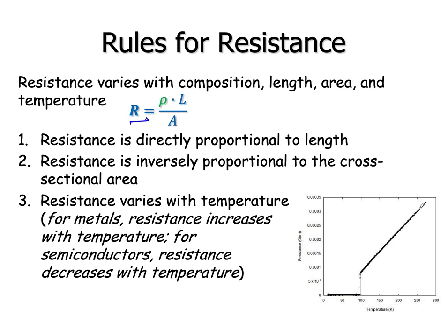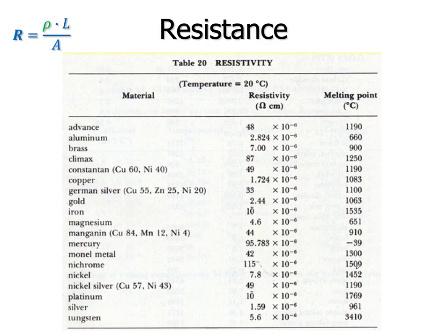The one other thing I want to mention here real quick is, for most metals, something very strange happens. If you get them cold enough, suddenly the resistance will drop to zero. What's happening at that point? At this point, it becomes something with zero resistance. It becomes superconducting. All metals have a critical temperature. Most of the time, it's only a few degrees above absolute zero, 4, 5, 6 Kelvin. At that point, it becomes a superconductor. Above that point, it has some resistance.